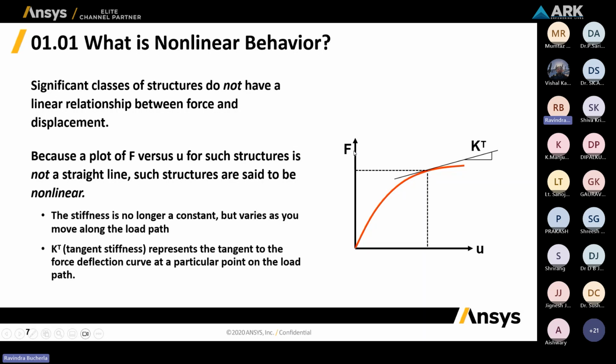Whatever force we apply, the stiffness matrix K will not be constant. Because of this, the deformation will not increase linearly with respect to force. This is the difference between linear and nonlinear analysis: in linear analysis the stiffness is constant, and in nonlinear analysis the stiffness is not constant.